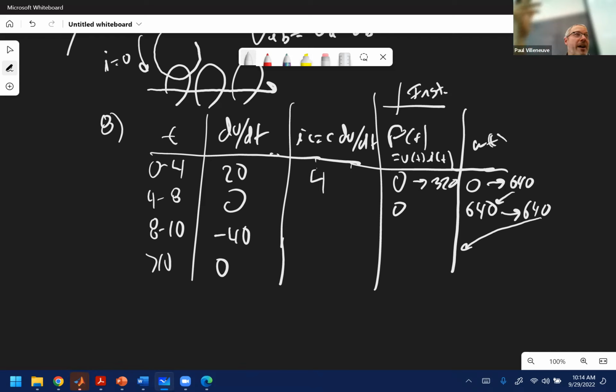And when we start talking about capacitors and inductors that have the ability to store energy in electric and magnetic fields, that stored energy has to go back at some point because it's not doing anything with it. So unless you just keep the capacitor charged forever, you have to send it back. So in AC systems, at some point your capacitors are being charged, and at some point they're being discharged. And how you take that into account with average power is you come up with a term called reactive power or imaginary power. John might talk about that when you get exposed to it in 312.